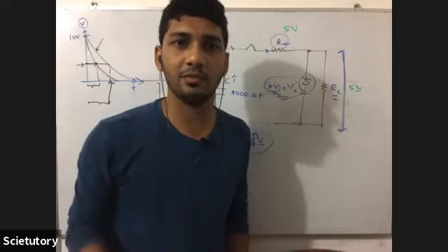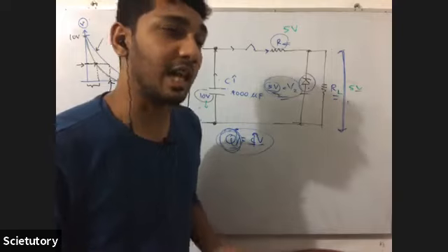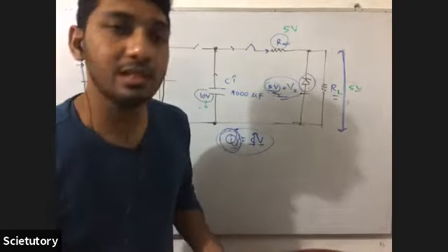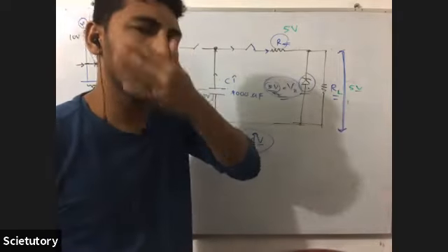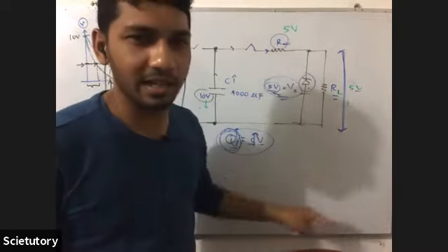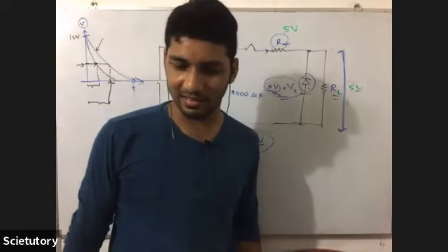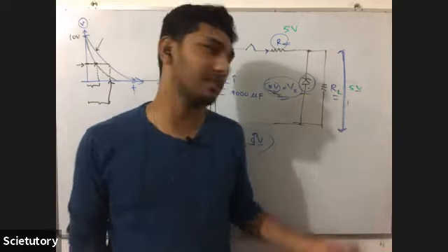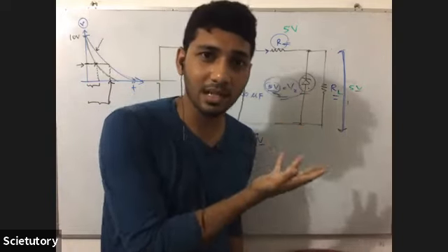Capacitance. It has. When you increase the capacitance, the charge stored is increased. The time taken for the discharging process is increased. The time through which the Zener diode remains broken increases. Then what they are telling in the B statement also increases: the time period through which the voltage across RL remains constant. So the voltage remaining constant means the Zener diode remains broken.